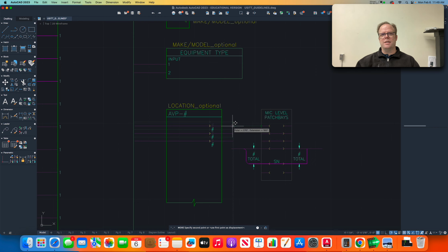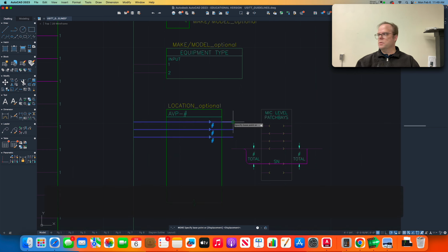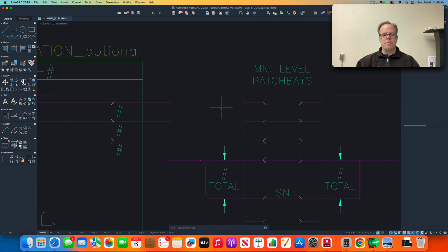Did you see that? I'll do it again. So I'm going to move, select those, start with this top right line, and then hover over the top left line of the patch bay and track back to the vertical off of that. Then click. And now I know those are lined up. Then I can extend to boundary edge for those lines. Boom, boom, boom. And there they are.